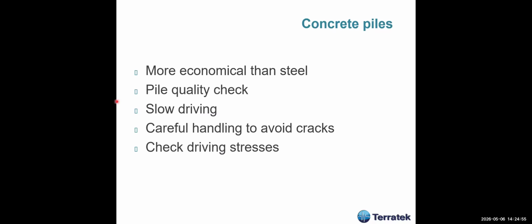Okay, and check driving stresses. This can be done by dynamic pile testing that we're going to discuss. Of course, you have to do pile load tests in order to check whether the pile is okay or not in relation to the design loads.